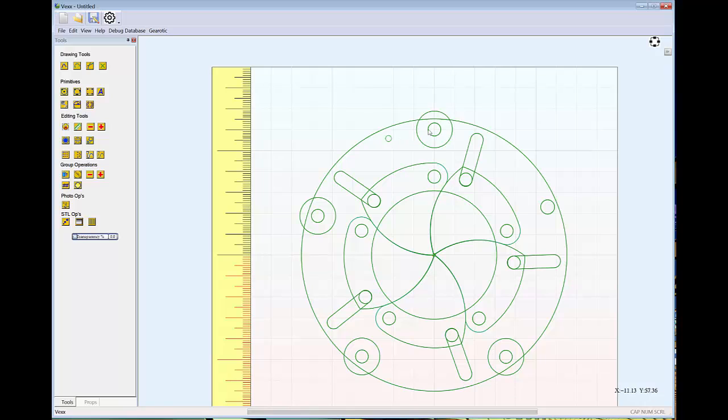So now we need to draw an arc between these 2 points. And we'll do that first by finding proper center for them. Just draw temporarily a circle out to here. We will make an arc from the center of this circle to the center of this circle and snap it to that circle, to the large circle. We can now select the large circle and delete it.